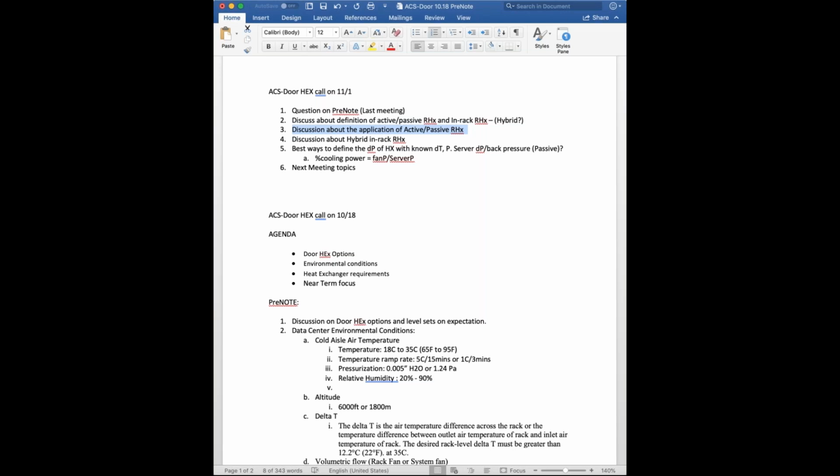So it's also very robust from a reliability point of view, because there are no controls needed for airflow. And the gain is the hot zone is within the rack, so you're able to go higher than in a normal data center where you have to allow a maximum for the hot aisle because people have to be there. And here it's contained within the rack. And once it leaves the coil, it's room temperature again. It's inlet temperature again. So that has to be the benefit. And of course, resilience. If you have a lot of racks, say 100 racks or more in a room, and you lose one back door cooler, you only lose 1%.